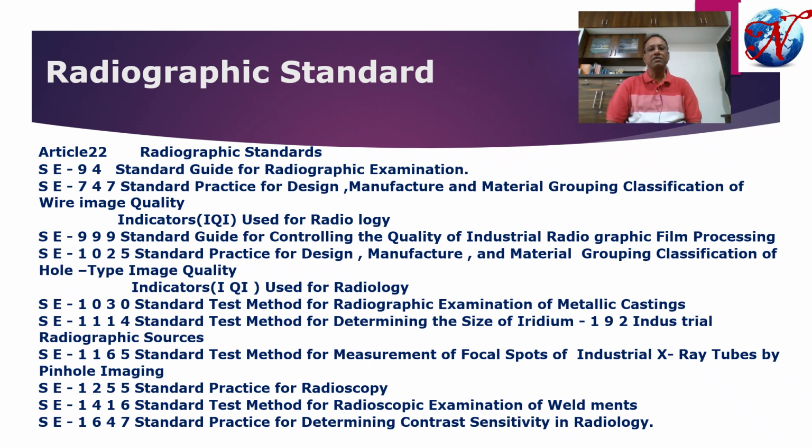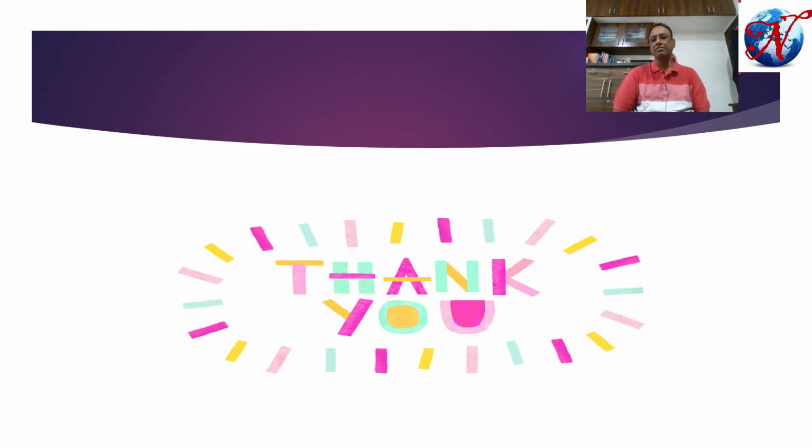SE-1255 is the standard practice for radioscopy, SE-1416 is the standard test method for radioscopic examination of weldments, and SE-1647 is the standard practice for determining contrast sensitivity in radiology. So these are the types of codes you can learn for the betterment of your knowledge regarding film interpretation.